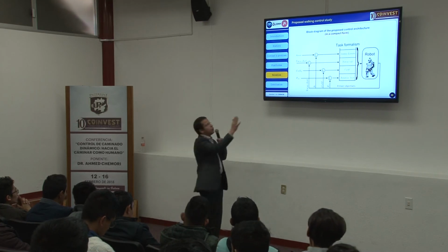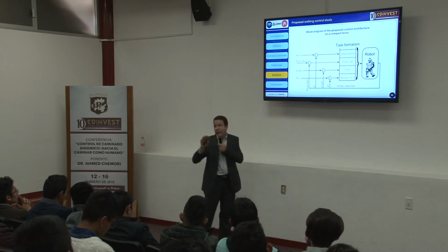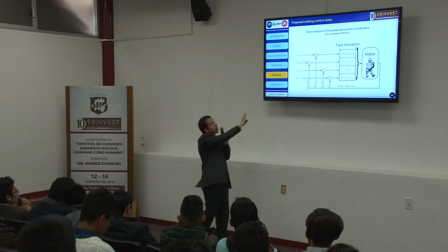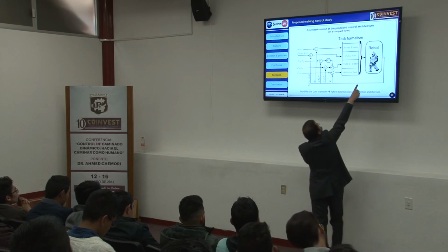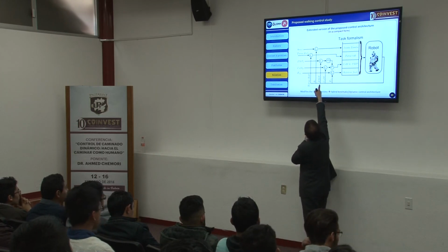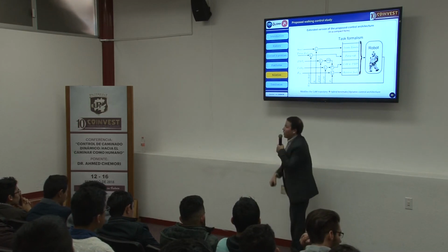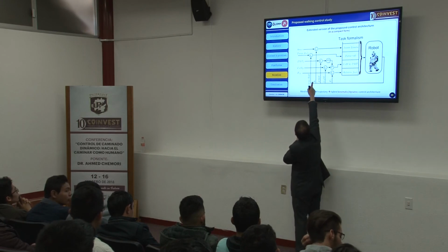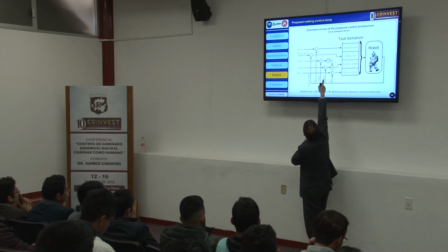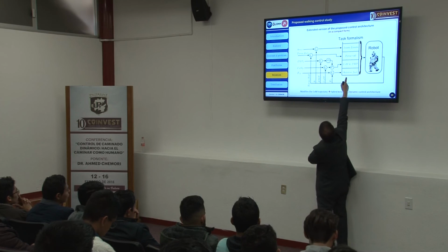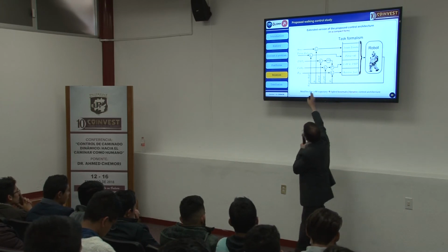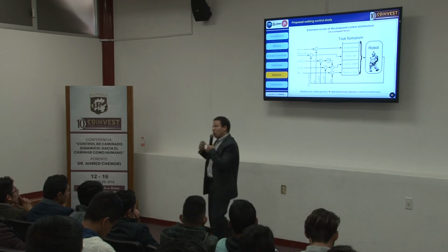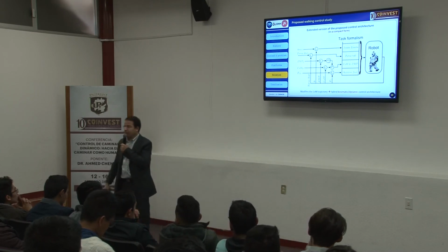But actually, the motion that we obtained here was not enough to keep the stability. This is just kinematics, so we have to add this. This is the measurement of the contact forces. The desired ZMP is in the middle of the support polygon, and then the nonlinear PD controller is added to the center of mass. With this architecture, kinematic and dynamic, we do the motion while keeping the stability.